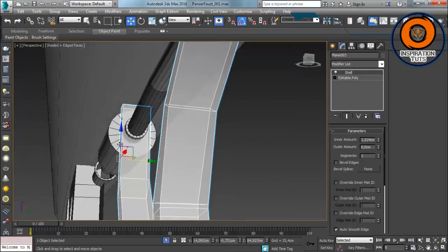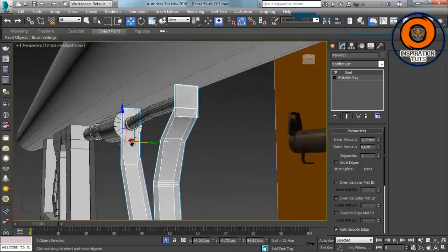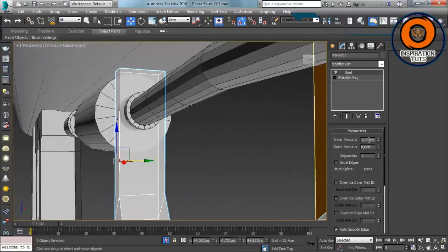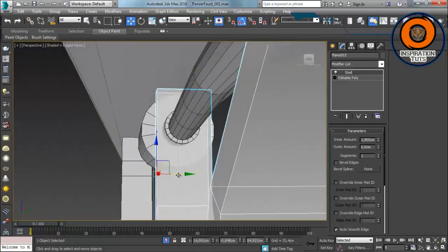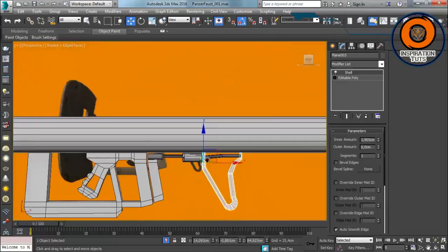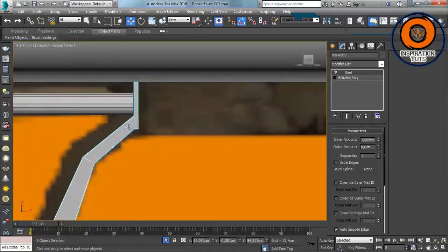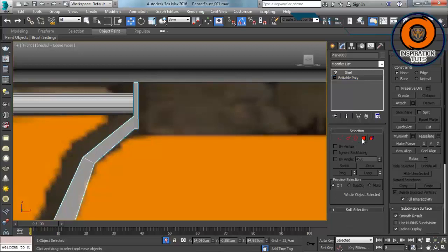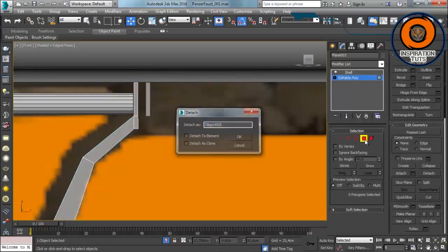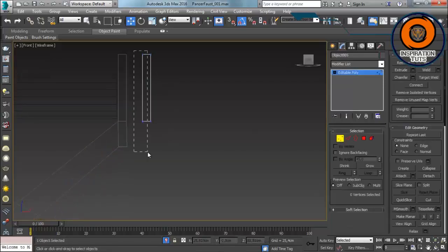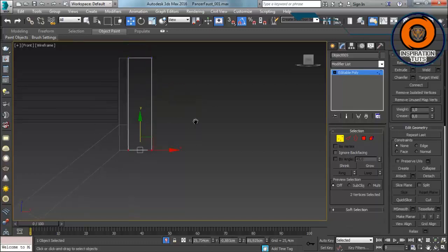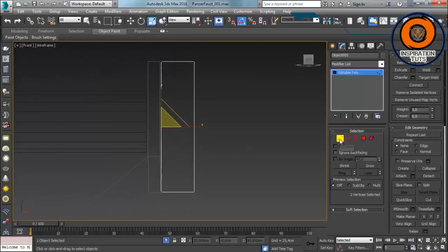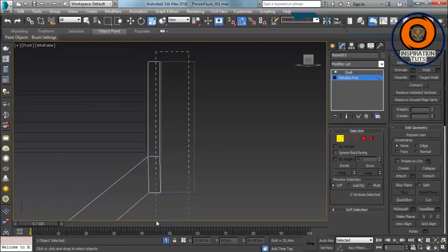model a little bit more thickness, because thickness is a really important thing to transfer from 2D to 3D. And I think the shell modifier is extremely important if you are in need of something that takes you from 2D to 3D quickly, instead of using the extrude modifier, because the extrude modifier is going to leave an empty space in the back side.